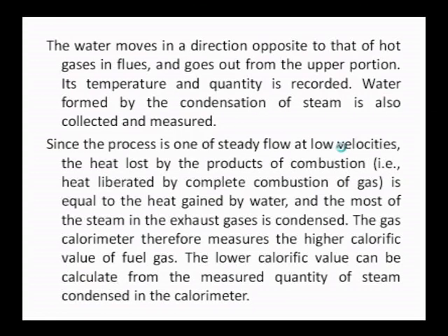Since the process is one of steady flow at low velocities, the heat lost by the products of the combustion, that is, the heat liberated by complete combustion of gas, is equal to the heat gained by water. So, in order to understand the calorific value, this point has to be understood. Whatever heat is liberated by the gas is equal to the heat gained by the water, and most of the steam in the exhaust gas is condensed back.